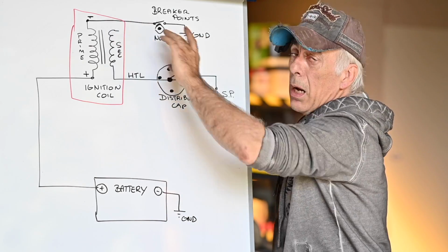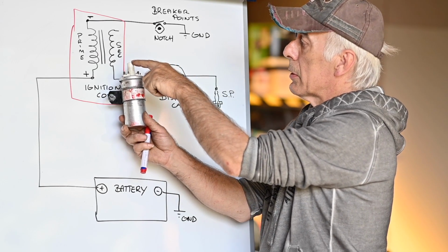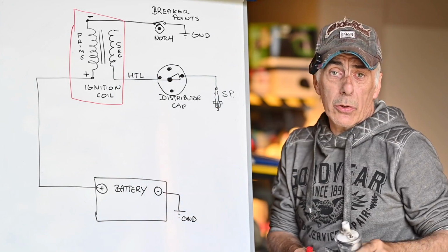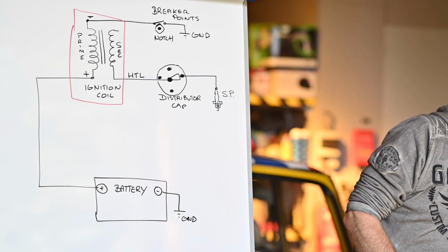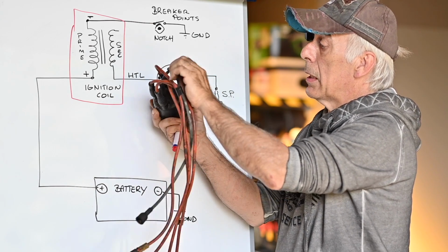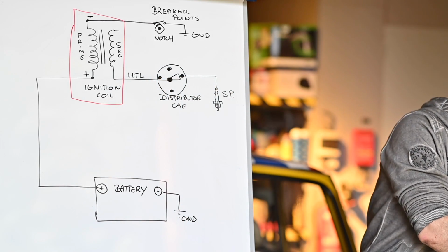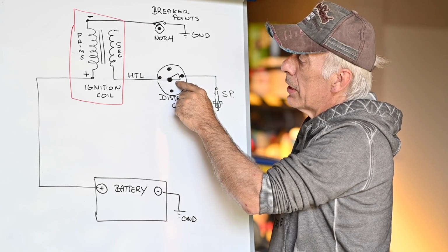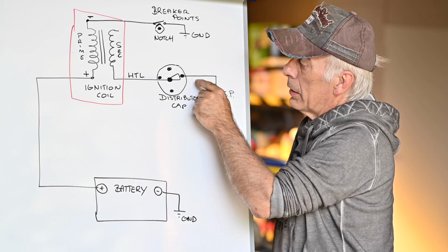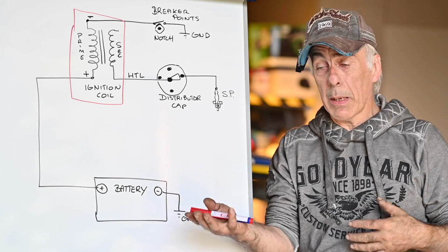On the secondary winding of the high tension coil, which is this output, we will find the high tension lead. And the high tension lead typically connects to your distributor, which is the middle connector of your distributor, right? This kind right here in the middle. So not the one that is going to the individual spark plugs. And inside the distributor we have the rotor, which is this part, which then will distribute the spark to the relevant spark plug. And of course this is the lead going to the spark plug itself, and we have this 4 times or 6 times or 8 times.